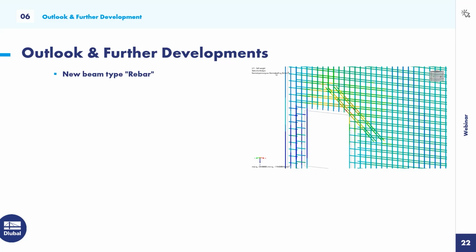You will get the stresses and forces in this member. If you work together with the nonlinear material behavior, with the damage elements, then the concrete is considered cracked, and the reinforcement will take all tension strains, and you can also design, for example, deep beams or some walls.